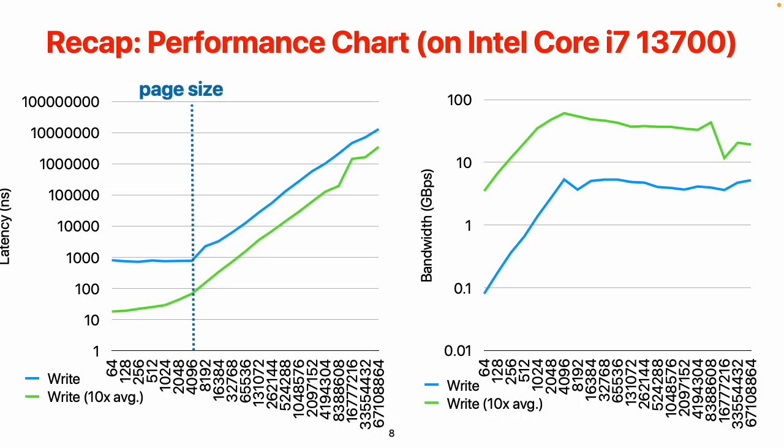The row buffer is exactly the size of a page, right? So what that means is that no matter what you read, as long as it's smaller than the size of the row buffer, I will have to wait for the DRAM to fill the whole row buffer before I can do anything, right? So everything below 4K is probably going to enjoy the same latency, right?